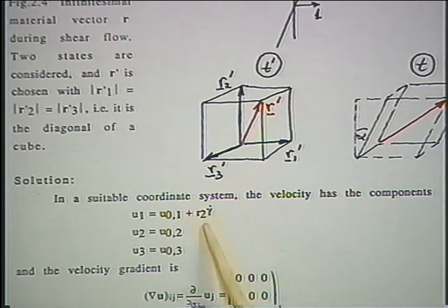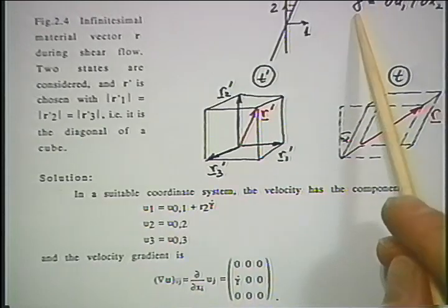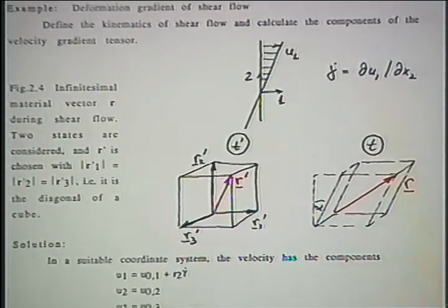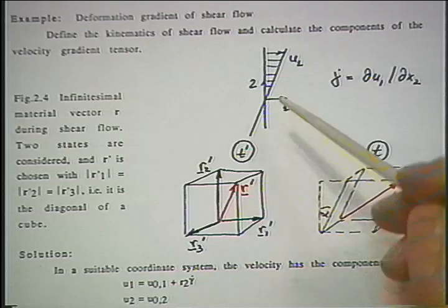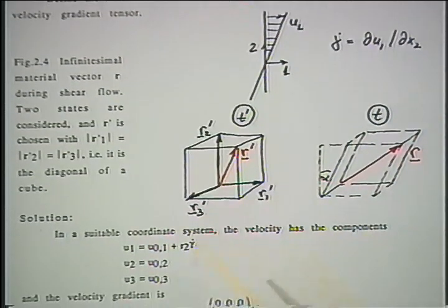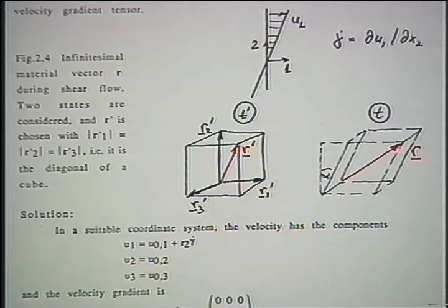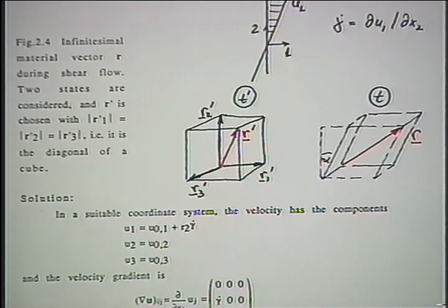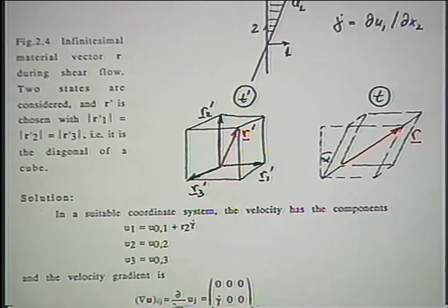And the moving up is given by the shear rate, gamma dot, which is equal to the velocity gradient. So the distance R2 times the velocity gradient gives us the new velocity. While the velocity sideways, say in two direction or three direction, is constant. Or in most cases, the velocity sideways is 0. In this application, which I drew on the blackboard, the velocity is 0. Any questions?